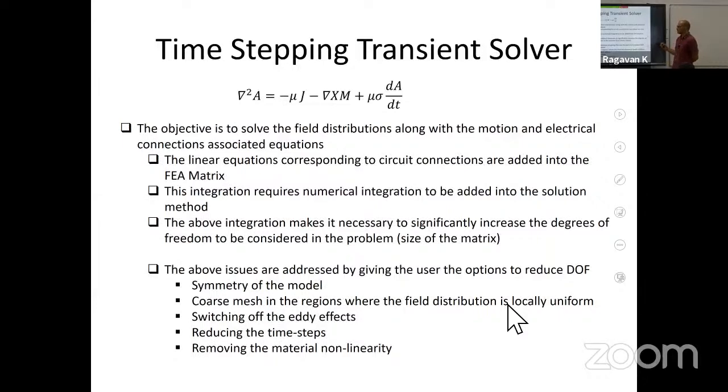So basically, in some cases where I was simulating for 1000 hertz frequency, I found that the estimated resistance is dependent on the time step. So there are so many errors inside, with the circuit and numerical integration, everything happening. So it's a black box. We don't know what the estimated value is. The only thing that we are relying on is the convergence. So as you keep on reducing the time step, you have to make this benchmark simulation to find what is the minimum time step you can use.